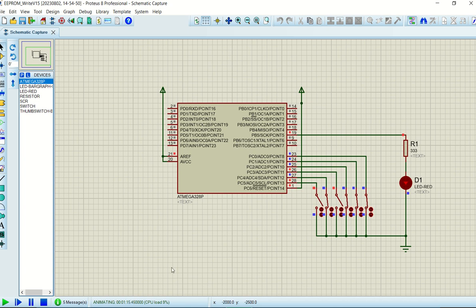And this is how you do EEPROM writing and reading when you make use of this. You specify the hex address of where the data must be placed and where it must be read from. In a follow-up video, I'm going to show you how it is also possible to make use of a header file, and then you don't use the addresses, the compiler will actually decide where the value will be placed if you assign a name to it. So I'm going to discuss that in the next video. Thank you.